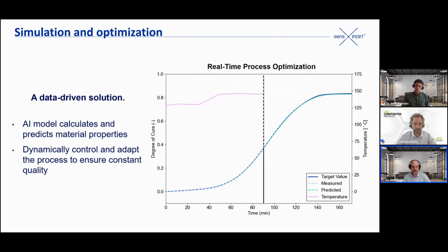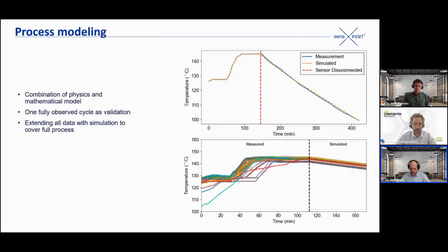And the problem we had is that we had to combine our simulation and measurements, because when I got the measurements the first time, they always stopped after like 2 hours. And the degree of cure was way too low. So when we came to visit the customer, they showed us that after the molding step, they left the part in the mold, took it out, disconnected the sensors, but left it there for 10 hours.